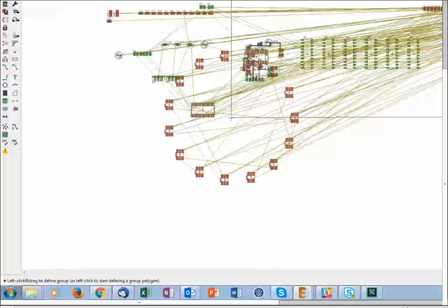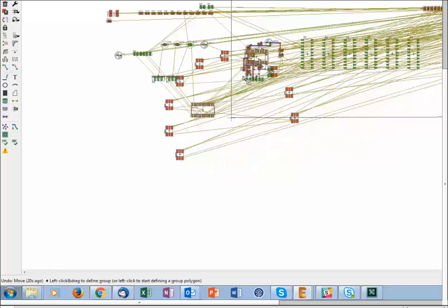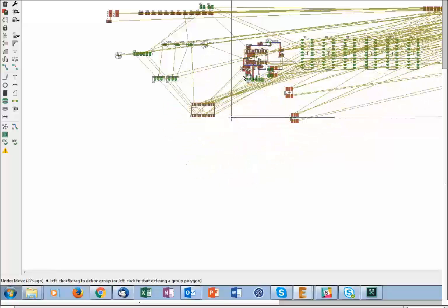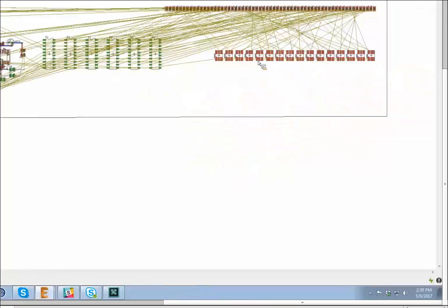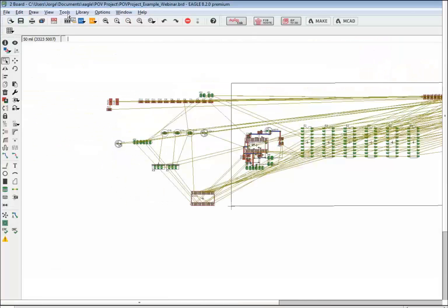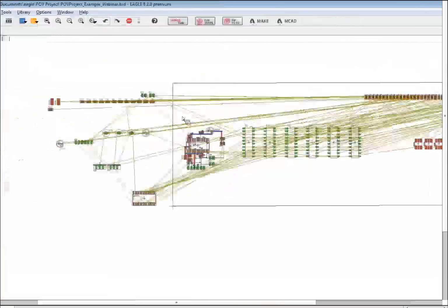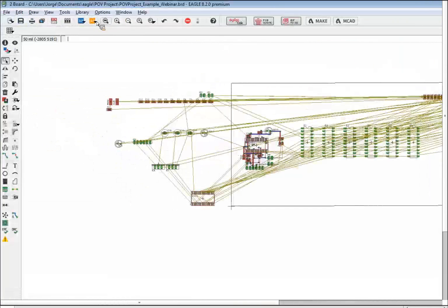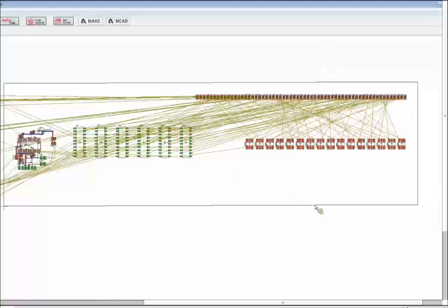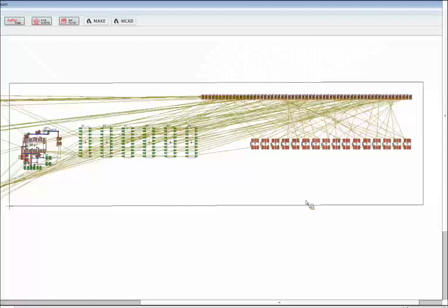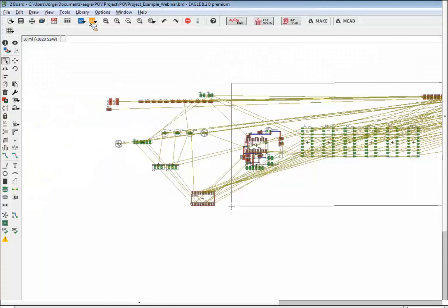Obviously, I just picked a random point, being 0, 0. If I do the operation again, then I can have it point towards the center. Do a Command Z, because the ULP basically is running a script that causes everything to move to the right spot. So we could do the same thing, and I'll pick another point that's a little bit less crowded, like 9 inches and 0.